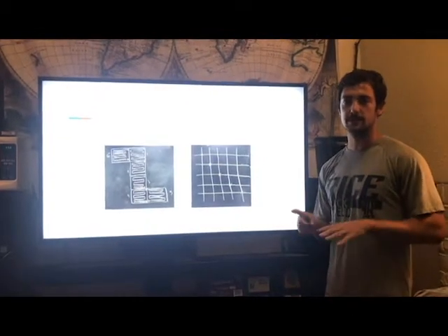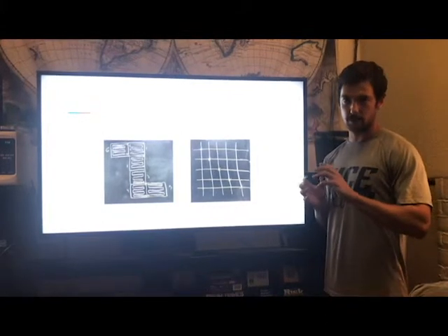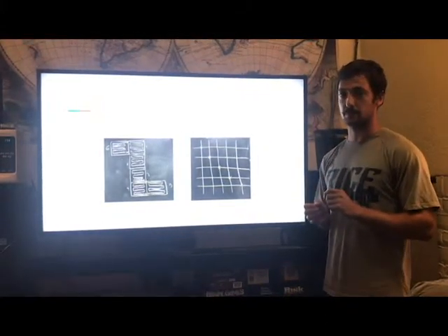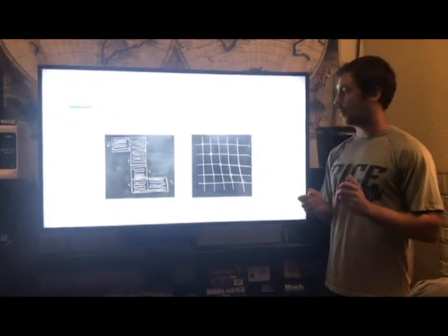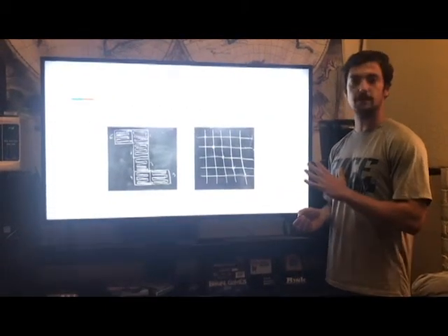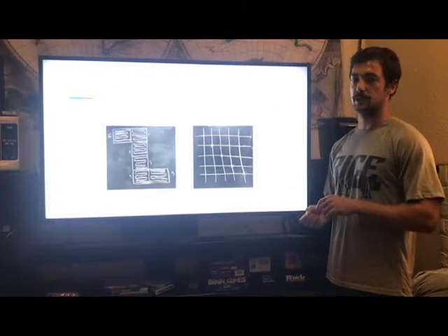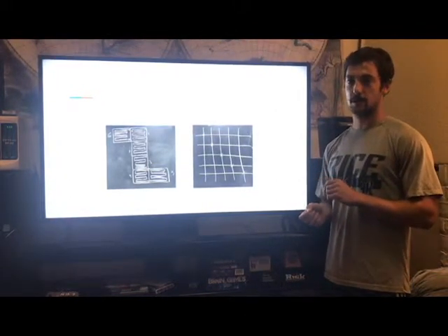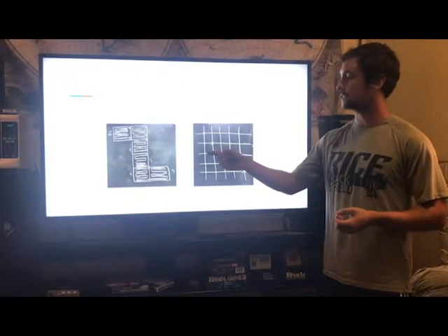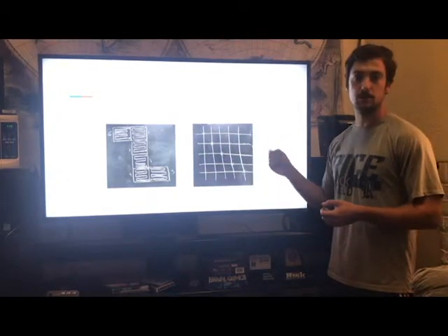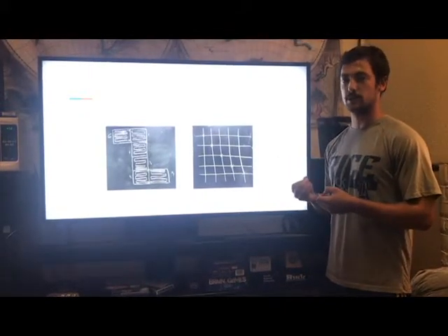With 5 buttons per face and 6 faces, totaling 30 buttons, we needed an intelligent way of being able to interface with buttons specifically, but also without being too hazardous with just throwing traces around. Our result was having 5 traces going vertically and 5 traces going horizontally, where each vertical trace was connected to one and only one horizontal trace, which would correspond to a specific button. For example, button 1 could be connected to this far left and top trace, and it would only be allowed to communicate through one of those traces.